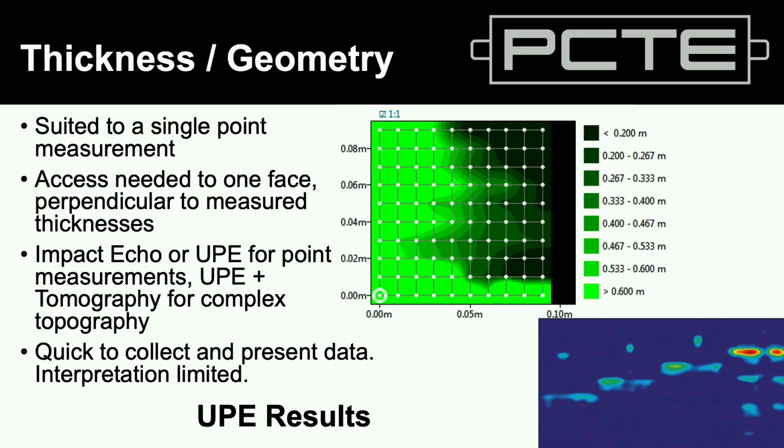So the pulse echo results, the lower blue chart is a slice, like a radar slice through. It's quite heavily processed because the technique pulse echo devices use is a form of synthetic aperture imaging. Essentially, similar to radio telescopes where you don't have one big lens, you've got lots of individual point receivers and a mathematical lens. We do the same thing with the arrays. We make more out of the shot than we'd otherwise have.